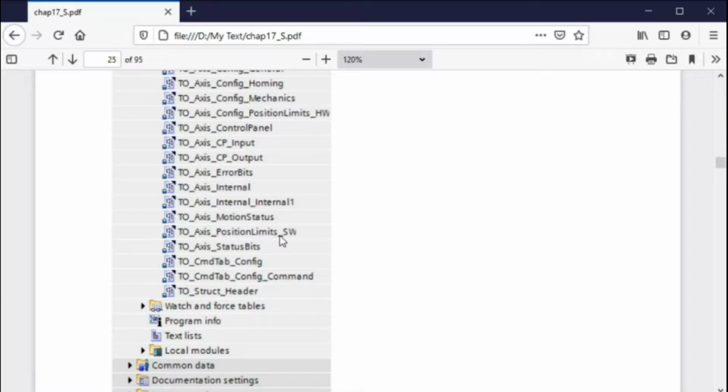Now, if you find that you have a different version of the software, if you were going from version 11 to version 13 to version 14 or version 16, that's easy to do because it'll just upgrade to the next version. If you're actually moving from one processor to another processor, a 1214 to a 1215, then in a case like this, you can't just copy paste the various parts over because there's too many of them.